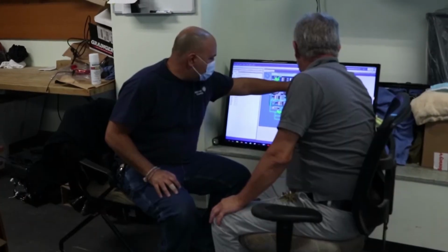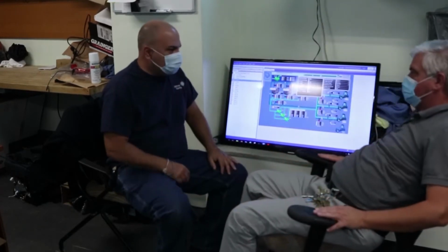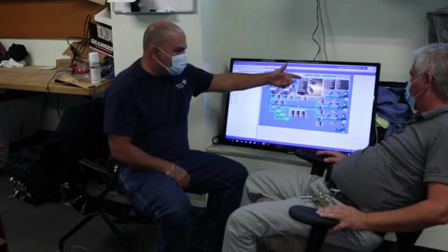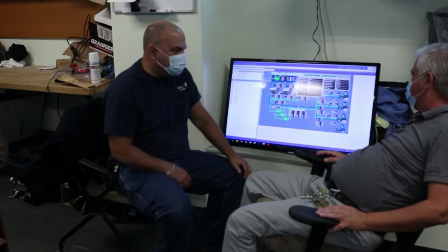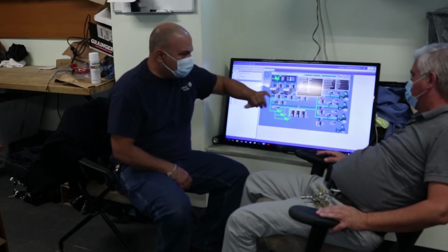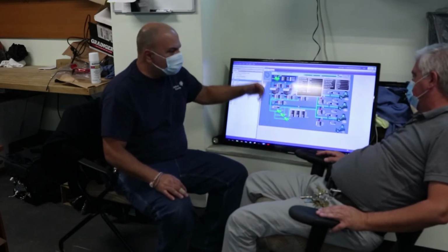It says cooling tower rotate, you go to true, and then manual rotate. So I would trigger it to true, leave it for like 10 seconds, and then put it back. Because it'll be on a schedule, that'll keep it on the schedule. But that'll rotate your towers.